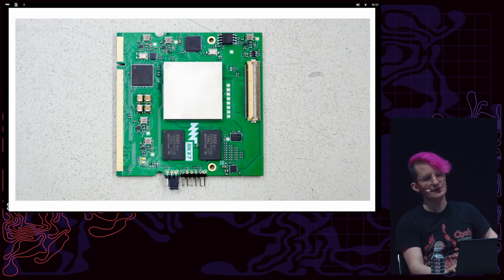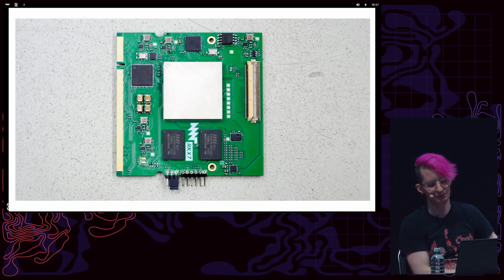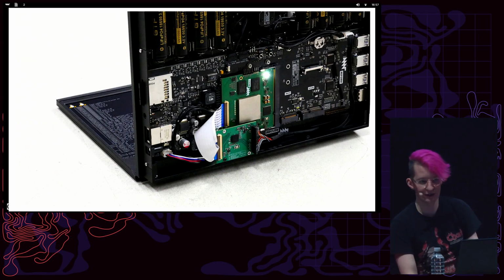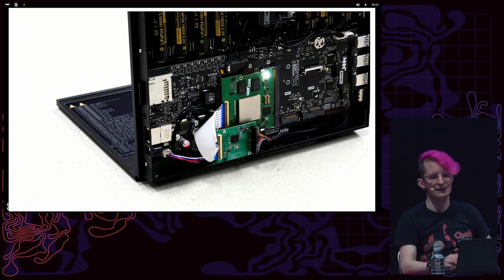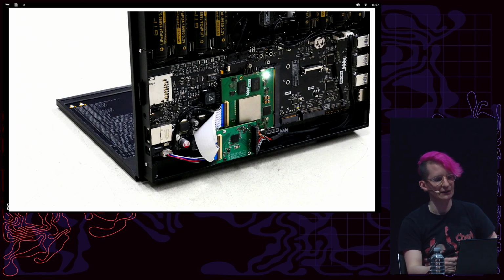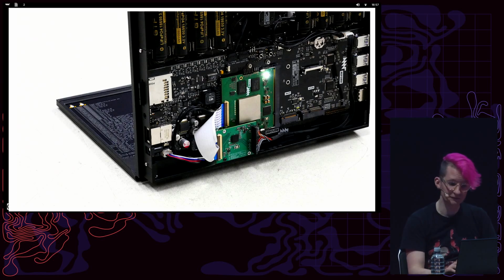Around the same time, I wanted something really pure at the heart of Reform, so I designed an FPGA-based module, the Kintex 7-based RKX7. It was also a time when there was a lot of activity in the open FPGA toolchain space around Yosys and LiteX and so on. I wanted to be able to say, here's a system where the SoC is open source at the gate level design. You can let it have RISC-V cores or Microwatt PowerPC cores or Motorola 68000 cores if you want. And it all worked out.